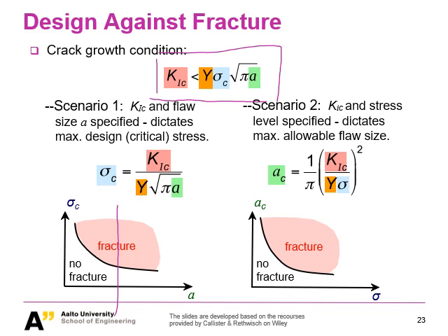And of course, the second scenario is when you have the constant K1C and you have a constant stress level, right, like that. And the loading is always fixed. And now, how can we avoid a fracture? Basically, you need to make sure in your material you don't have very large flaws, right?